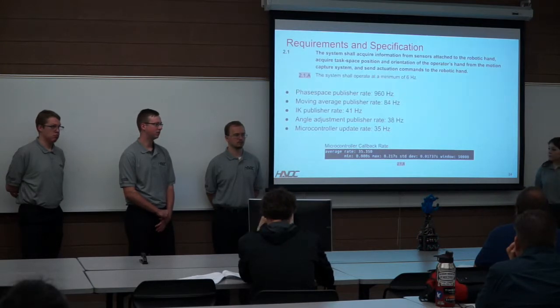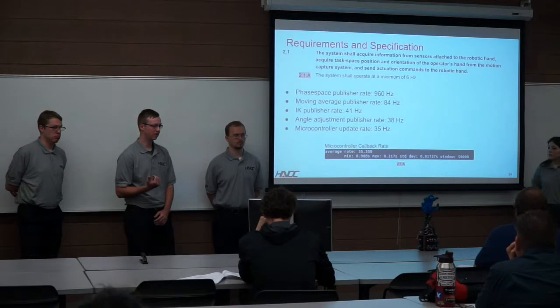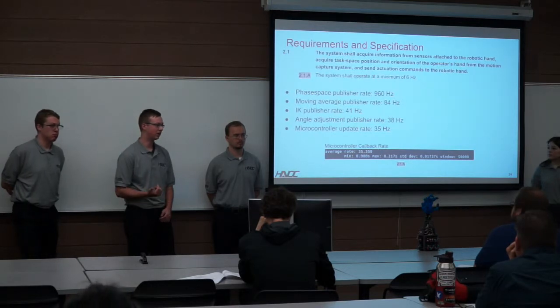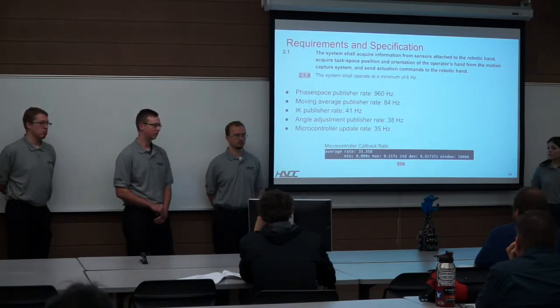For the servo actuation, we have to test. You have to test the fingers and how fast the servos can actuate those fingers. We'd attach the LEDs to the robotic hand and actuate a full finger as fast as we can, and we can get our data from that and test for the sampling frequency that we need at that point.